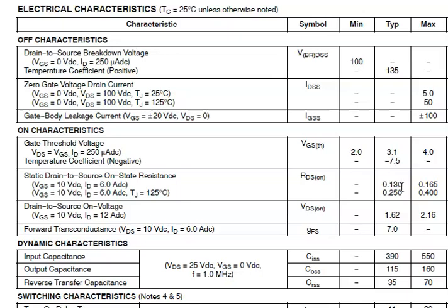But if you take these values as our initial consideration, it means that if the part is not passing in the line or production, we have to reject it. This is the issue of reject or accept when you work inside a production line in your factory. So if we take the maximum limit, we can squeeze some more in terms of design spec or allowable design criteria later. If we take the typical value, it can no longer be squeezed. So let's say we follow the example inside the notes. We just use the typical value, 0.13.